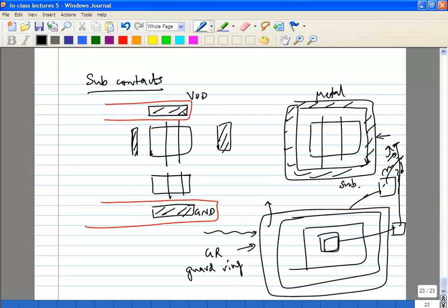So it depends on a number of things. It depends on the surrounding environment. It depends on the circuit itself. I'll give you an example. If you just take a switching inverter, it is going to be pumping something into the substrate. You want to keep its ground clean for the inverter to switch well. If you connect the substrate to its own ground, you may end up spoiling your own inverter switching characteristic. So there you may have to be careful.